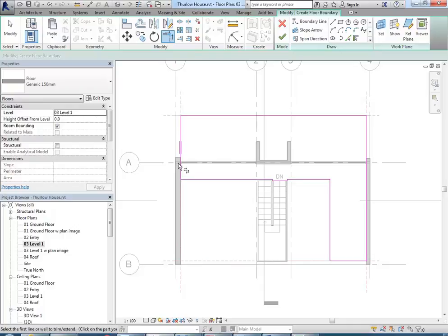Okay, so here you're trying to make that corner there. So choose it above. So that one, and then the one above. Yeah, to the left. That's it, there. Are they still on the page somewhere? Yeah, so you've got an extra line. So you see there, you've got to trim that line there to make this corner. So here, see this corner here? So you've got to use trim the corner. No, to the left. Yeah, other way. That line, and then line to the left. Yeah, it's like that line, but choose it on the left-hand side. That's it, there.